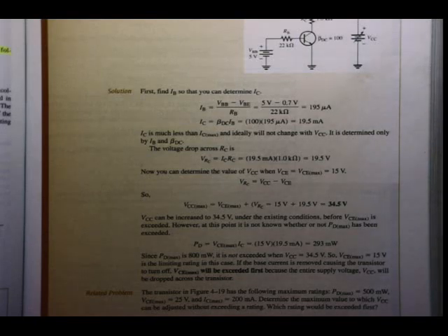Okay, so you can imagine if a device has to operate not at 25 degrees, but at some hot place, next to a furnace or whatever, where it might be 50, 75 degrees or whatever, this device won't be able to dissipate the heat quick enough. So if the power dissipation rating of a specific device was, say for instance, 1 watt at 25 degrees Celsius, it won't be able to dissipate enough power to still do 1 watt at, say, 75 degrees Celsius. It will have to be lower now because the surrounding temperature is much hotter.